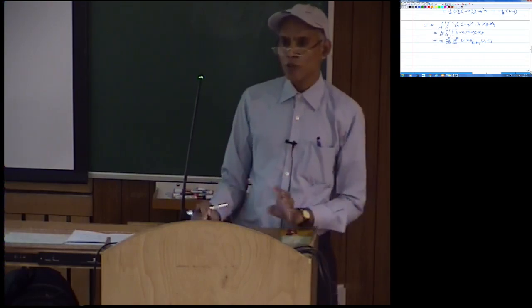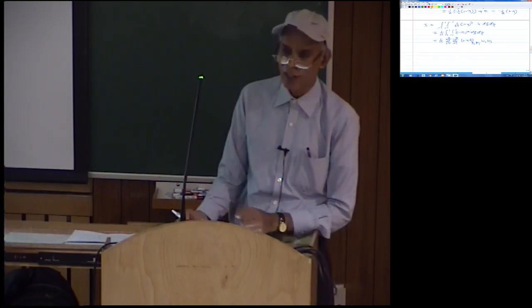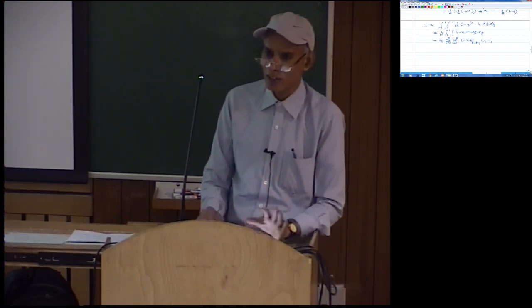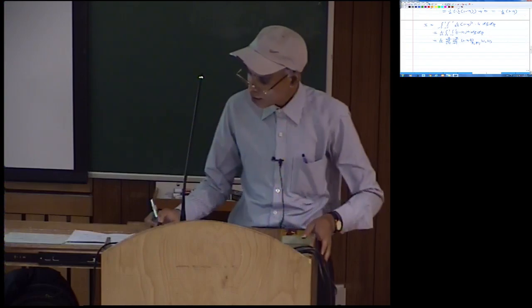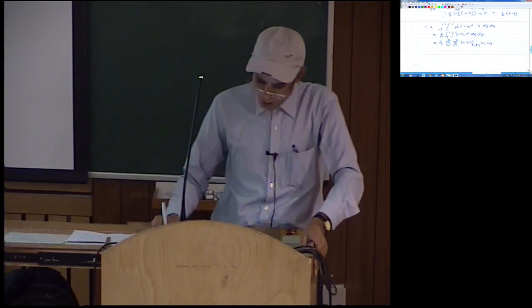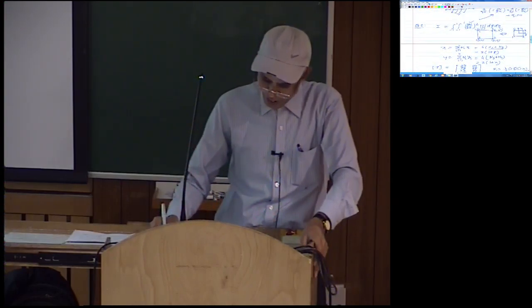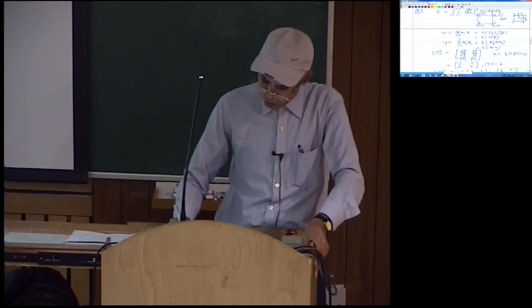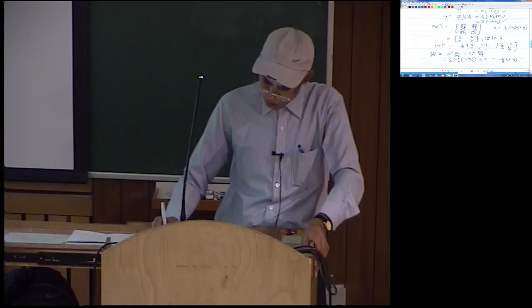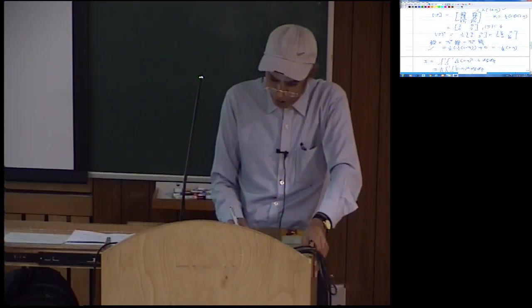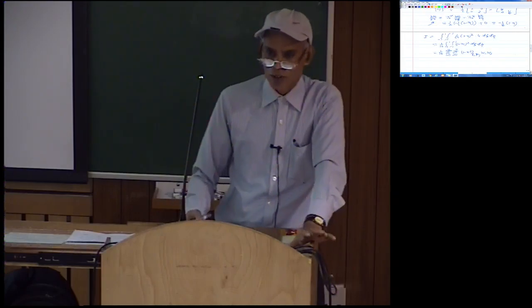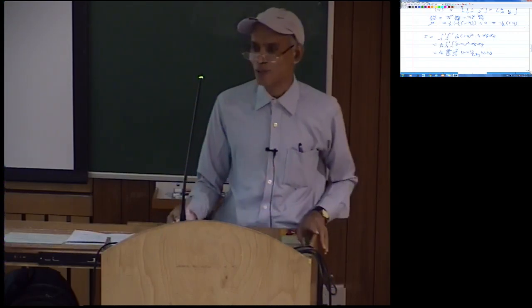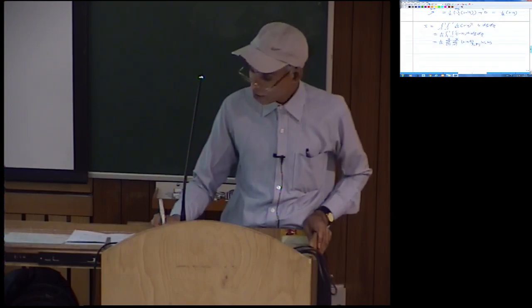Then this is going to be 4 terms. You evaluate this, finally it actually comes out as 1 by 3. There are 4 terms, you have to sum them. So see, why I asked this question was, it involves your interpolation for x and y, then it involves your Jacobian, your Jacobian inverse, then how to evaluate the derivatives of the shape functions, and then how to do the integration. And we had discussed all of this in the lecture classes.